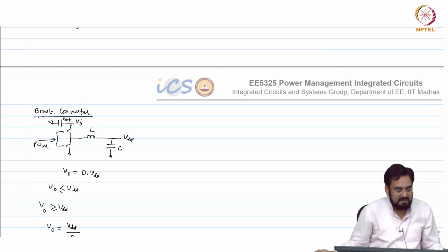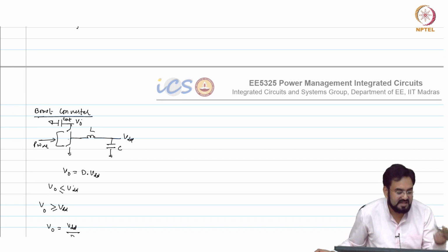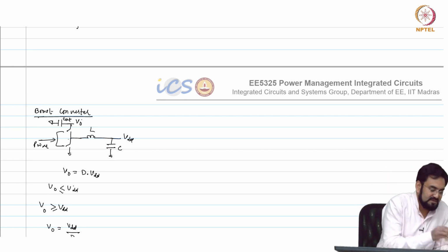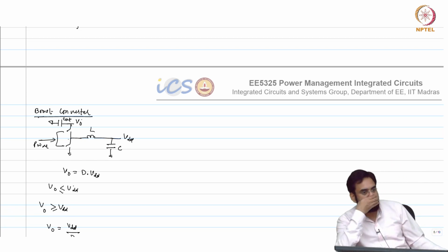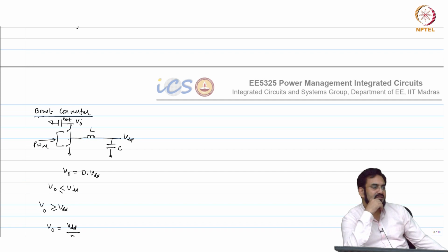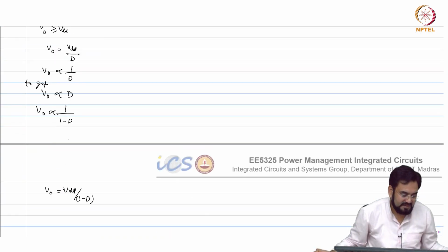and what is the, I mean high side switch is basically, which switch is charging the inductor? Think that way, the bottom switch or top switch? Which switch is charging the inductor? Bottom, huh? So which means your PWM duty cycle will drive the bottom switch, not the top switch. That's why it becomes 1 minus D. Okay.